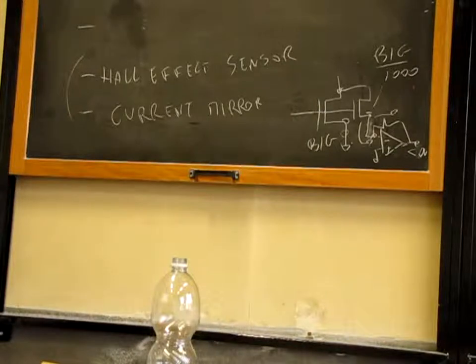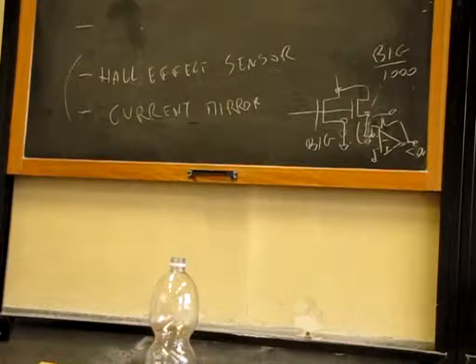You are reinventing a technique that is used, but it's not so easy. Because how do you want to measure the current using the inductor? Using the inductor as a transformer. Using the inductor that you already have as the primary winding of a transformer, you put a secondary winding on the same core, and you get some information about the current flowing through it.